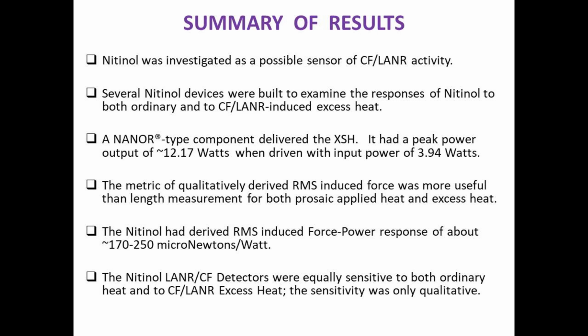Looking at the metrics that we could for nitinol, the induced force was the most useful as opposed to length measurements. The nitinol had a derived RMS induced force power response of about 200 micronewtons per watt.